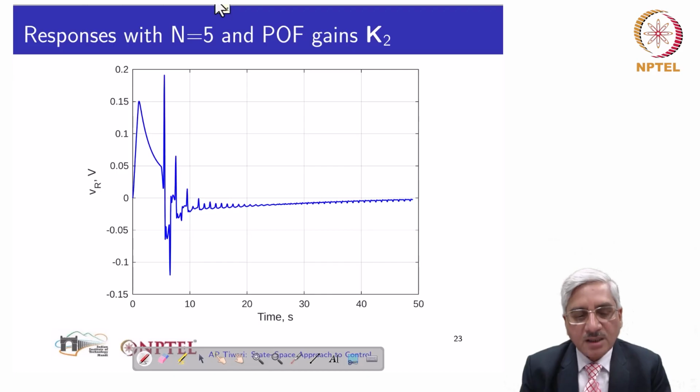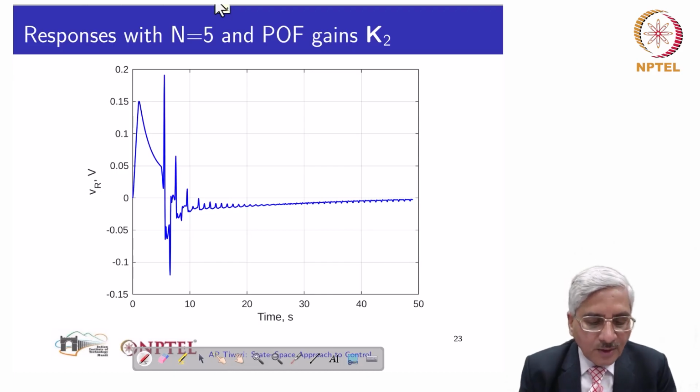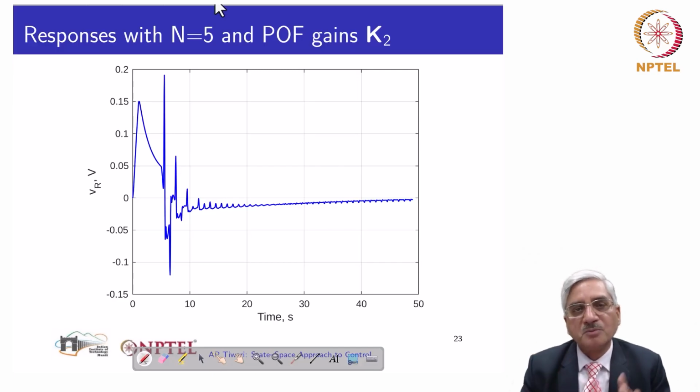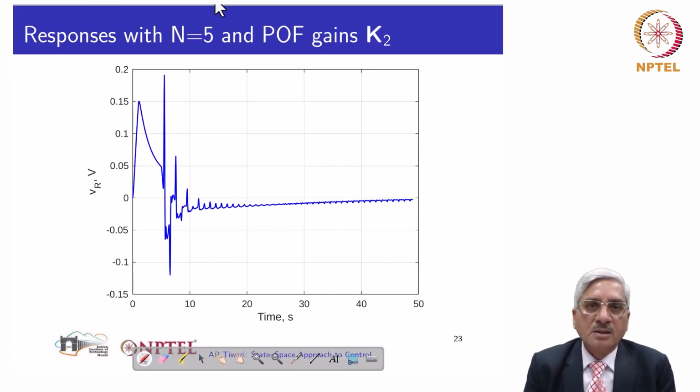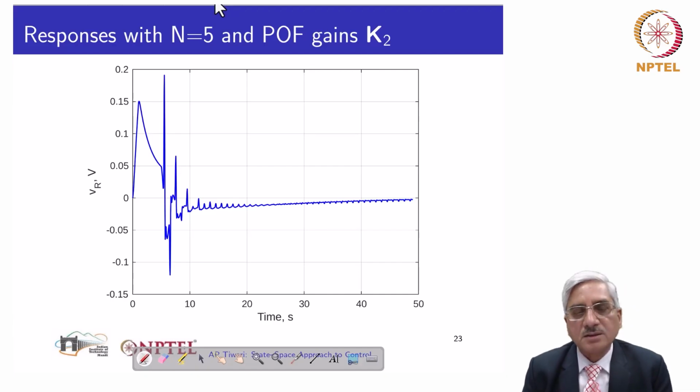Now with the larger gains, the only problem is that the control voltage swing between some minimum and maximum was large, much larger compared to that other gain which was smaller, which is a point of concern, of course, in control design. We generally try to get control variations which are not so high. So that is why I was telling this is a bad design.